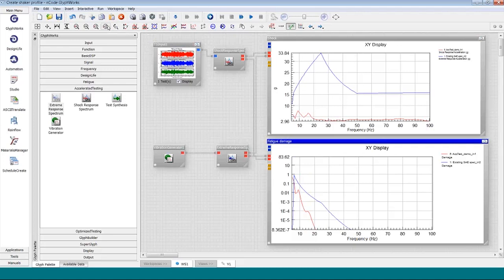So this helps us quantify or understand in a vibration sense and also in a durability sense, how have we been testing all along in a fatigue sense relative to the actual vibration that this part sees in the field? Similar information is seen up at the top here. This is the G plot that says G's versus frequency, so the worst case G loading versus frequency for the test spec versus the measured proving ground data.